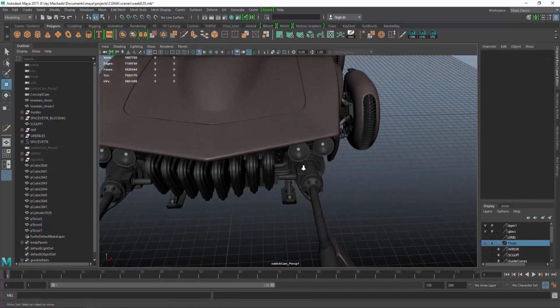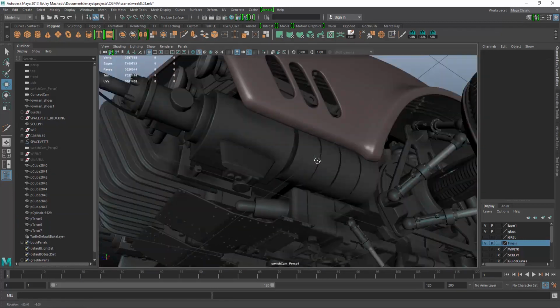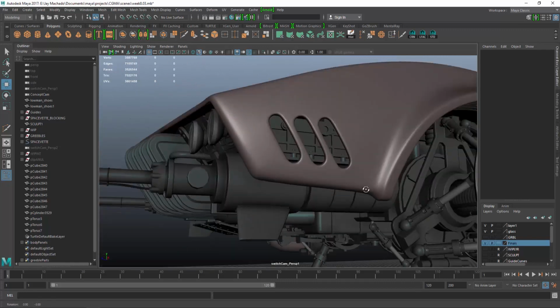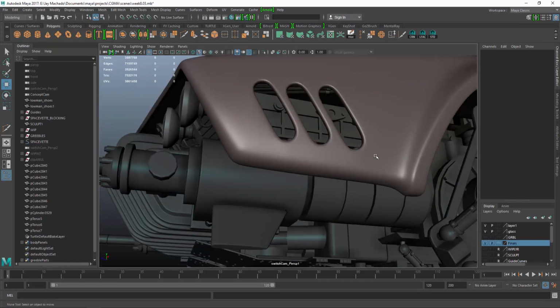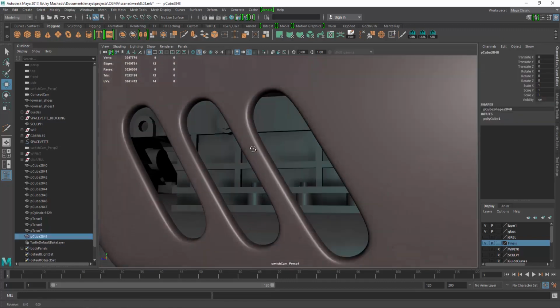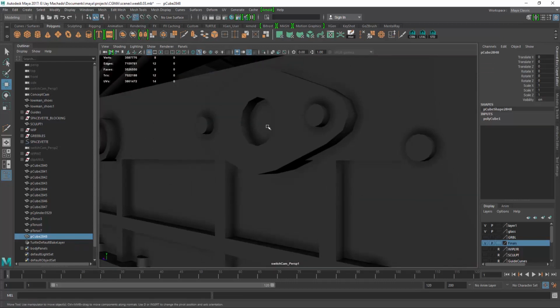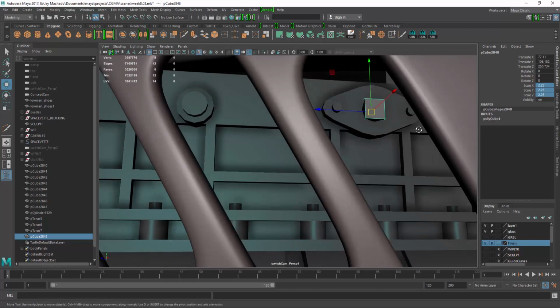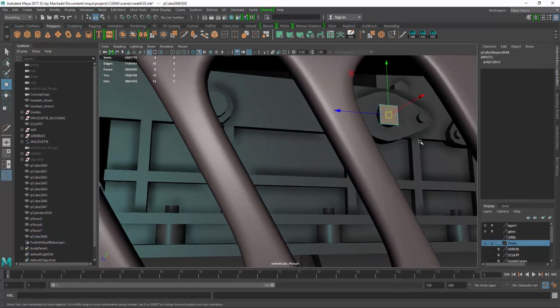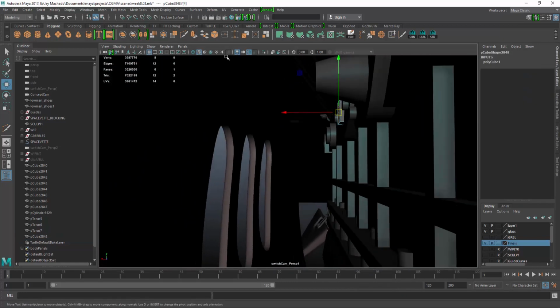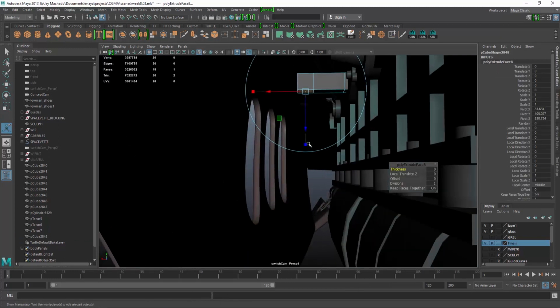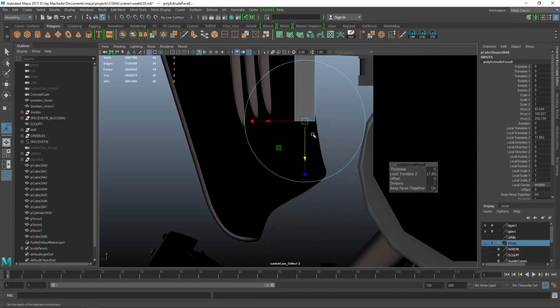And I think I want to add some pipes to this cylinder area because it's looking kind of boring. And we've got these little conduits up here that we can kind of connect pipes into. So I'm going to use my cube method. So I'll scale this 2.25. And then I can extrude and then extrude by 2.25, and that'll kind of create my junction points where we can change direction.